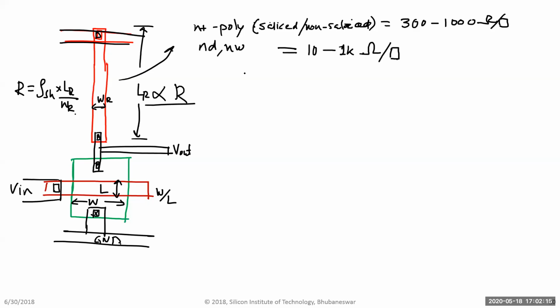Obviously metal you can use as a resistor, but if you take metal 1 or 2, they will typically be around 0.1 or 0.01 ohms per square, so you want them to be as small as possible. These are all the resistors you can use in a technology. But like I said, every technology varies. Some technologies will allow you to have what's called a high-resistance poly.